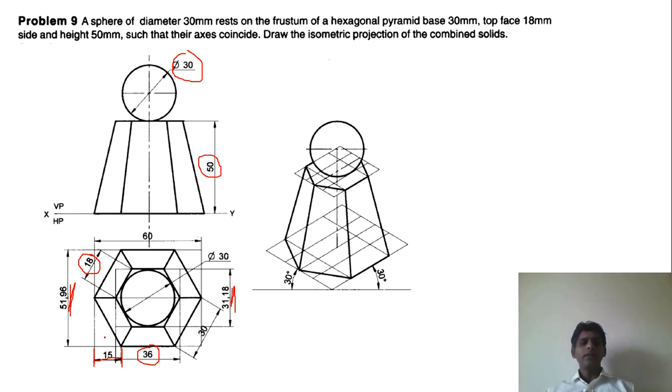So to get these distances, we have to draw this top view, right? And once you draw this, then you imagine that it is enclosed in a box, and you can take this as a reference, place this particular point and then measure this. You have to always convert it into the isometric length.